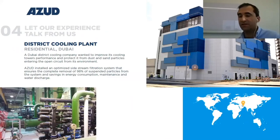the cooling system increased the suspended solids and the turbidity, which made nebulizers clog. Also, there was blockage of the cooling system panels. And of course, there was a high microbiological growth in the system. So maintenance time and spare parts increased, and there was also a decrease in the heat transfer of the cooling tower. This company trusted in our solutions to solve the problem.